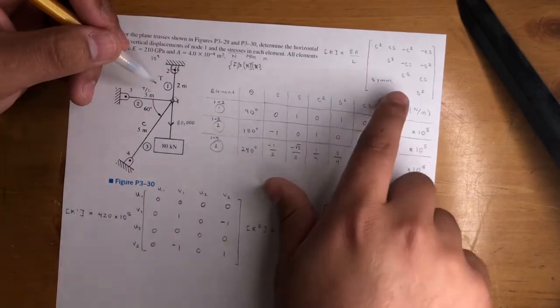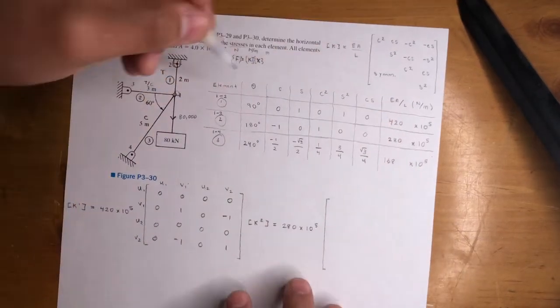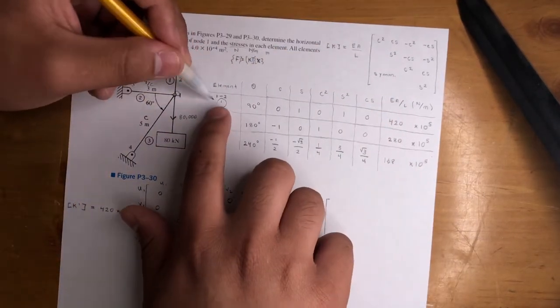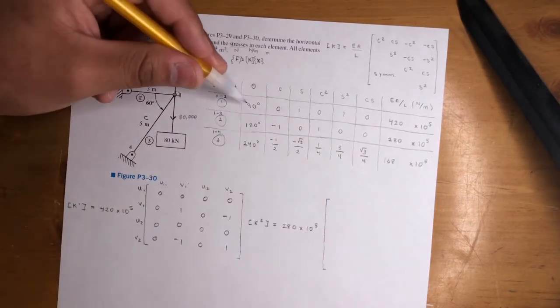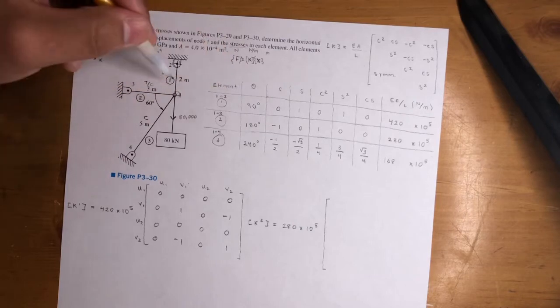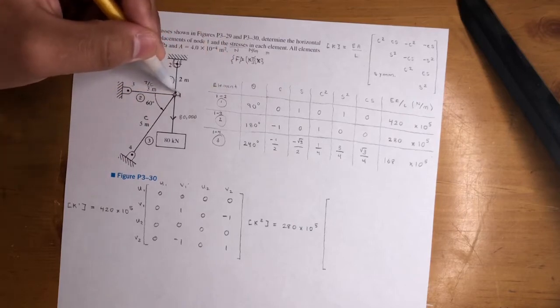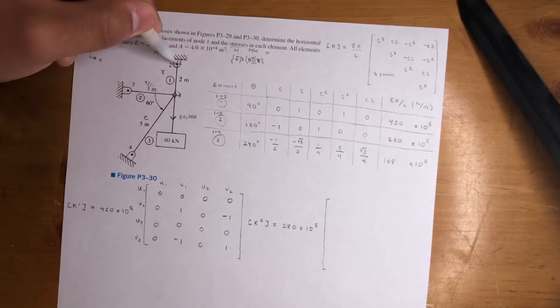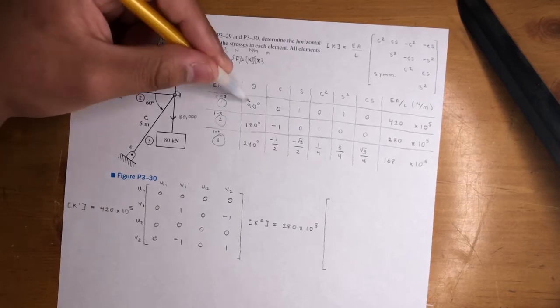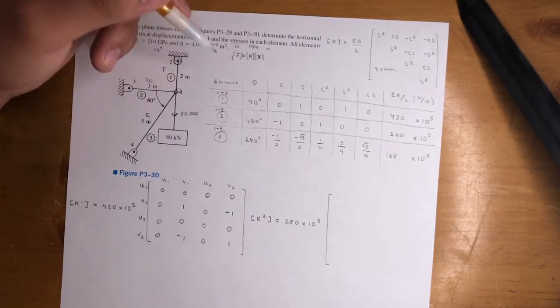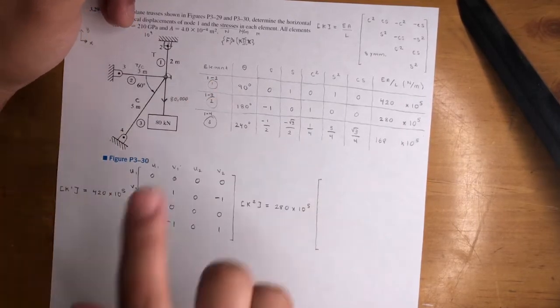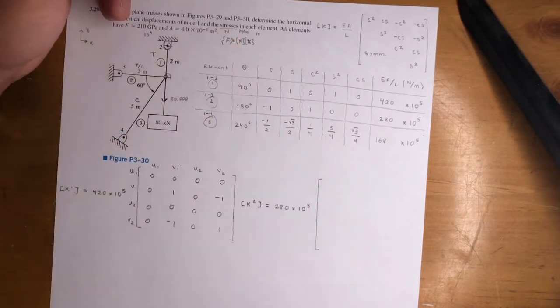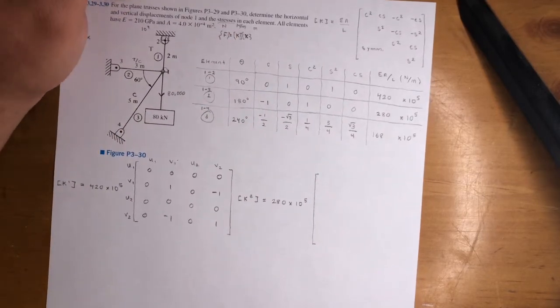So the stiffness matrix, going back, is going to be the same whether you go from 1 to 2 or 2 to 1, even if you switch the angle. If this case was 90, I think it would have been 270, remember we mentioned? So this was 270, you'll still get the same stiffness matrix and all that good stuff, but your stresses will kill you in the end if you do not follow this approach. So you need to do this if you're finding stresses or forces, just FYI.